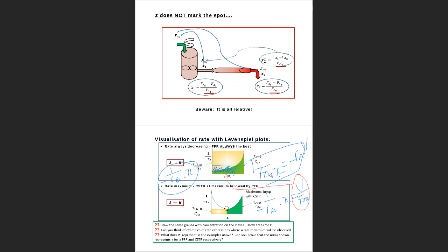Okay? And I can, of course, write this in terms of a concentration if I want, and the volumetric flow rate, which results in this residence time concentration issue. Right? But I'm normally, and this is a good question I had via email, interested in sizing my reactor. This is what it's going to be all about in this course: what is the volume that you need for that reactor? And how am I going to shape that reactor? How will it look? Will it be in tubes? Will it be fat? Will it be thin? So you've got control over how that reactor looks. But first off, you will use it to find that volume.